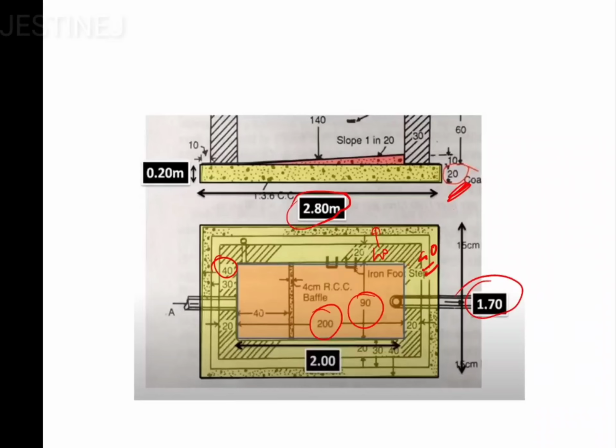Okay, so that is the case of the slab. Then the sloping portion, if you check out, its length is going to be this 200 centimeter or 2 meter. Inside portion only, slab, it is going to be the sloping surface, 2 meter only, and the height, how to take the average, that is 0 plus 10 by 2, you will get 5 centimeter.